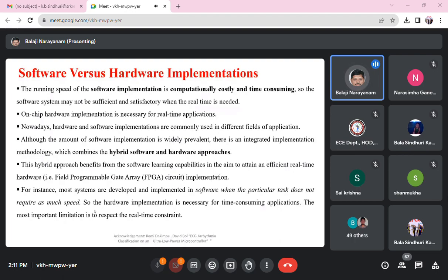See, why we can prefer FPGA is, as you know, they are reprogrammable and reconfigurable. Whenever I want reprogrammability or reconfigurable flexibility, better I may go for FPGA implementation. If the functionality is fixed and I don't want to reconfigure or reprogram the processor, then I may choose the ASIC implementation, as application specific integrated circuit implementation.